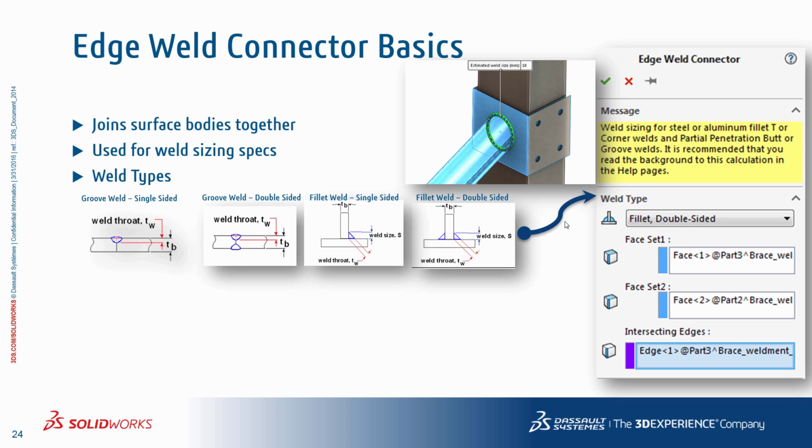The groove weld is a weld applied in a preformed opening or groove between the two metal parts. The groove welds defined can represent all edge-to-edge weld types like the square, butt, V, J, and U conditions as well. The fillet weld is a triangular weld that joins two metal parts at a right angle.